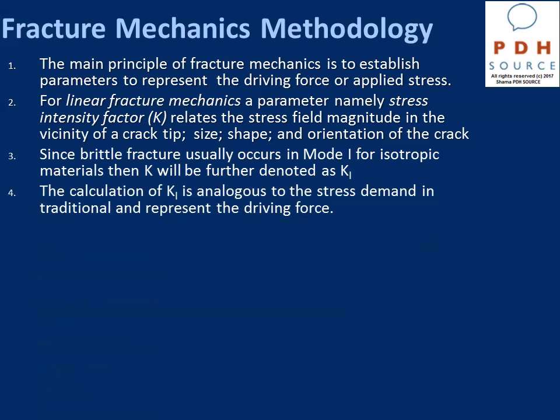Calculation of K1 is basically analogous to the stress demand in traditional structure analysis. In traditional structure analysis, we set structure models for our structures, run the models, and calculate the demand force in each member. So basically, K sub 1 is analogous to this process.